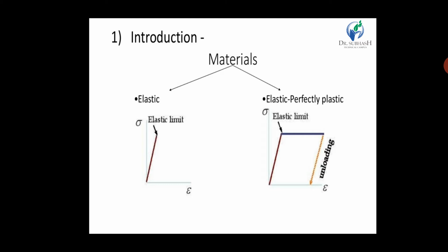You can see this in the graph of the elastic limit. The plastic method of design utilizes the reserve strength of steel beyond the yield strength up to the ultimate load point, so the plastic method gives a more economical design compared to the elastic method. That is why, in the revision of IS 800, the plastic design has been introduced for material safety.